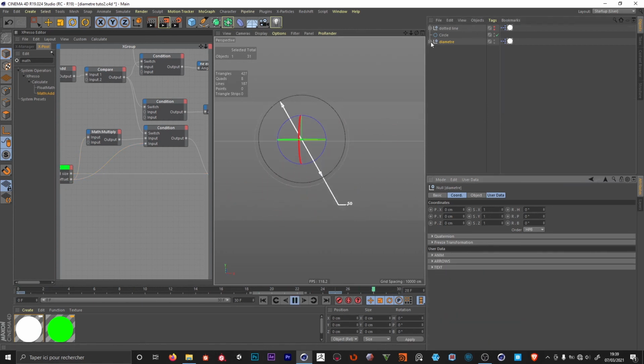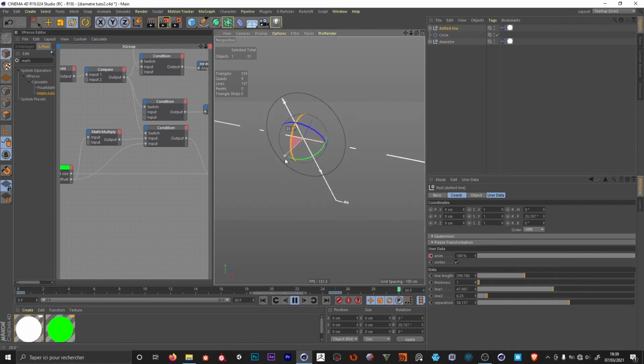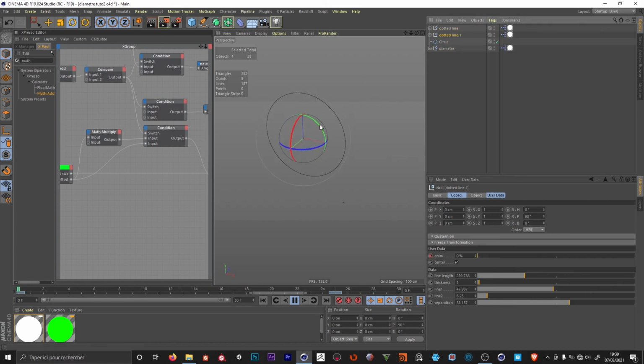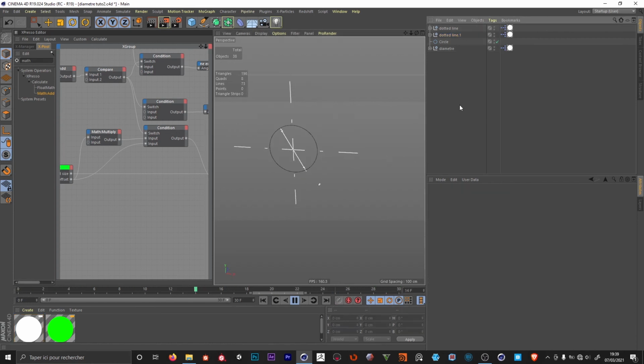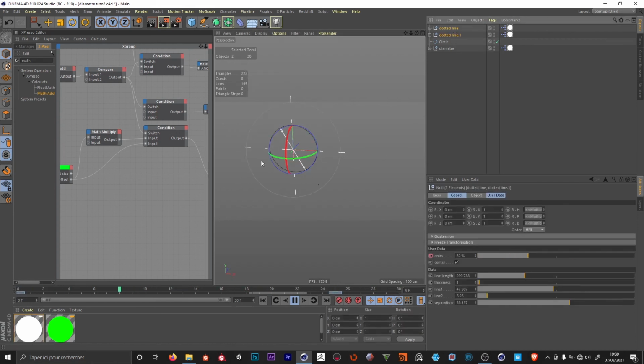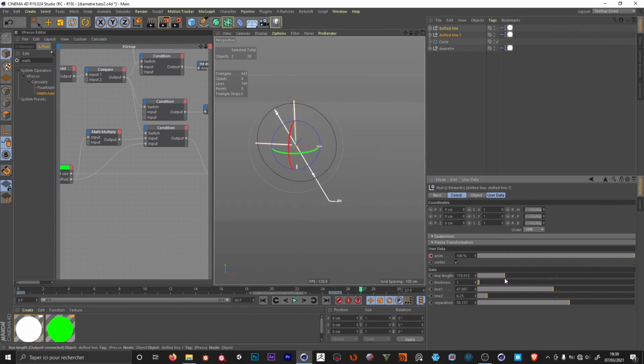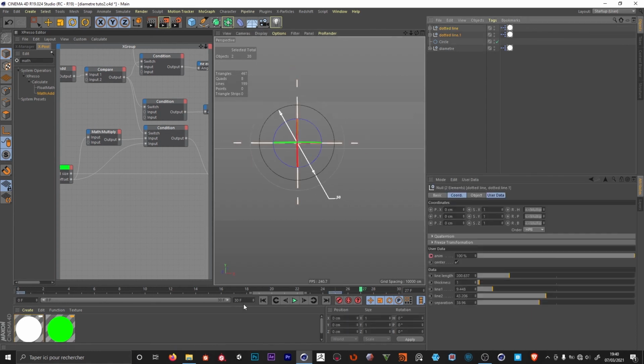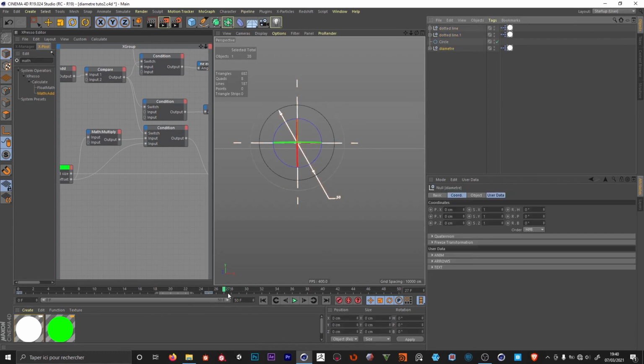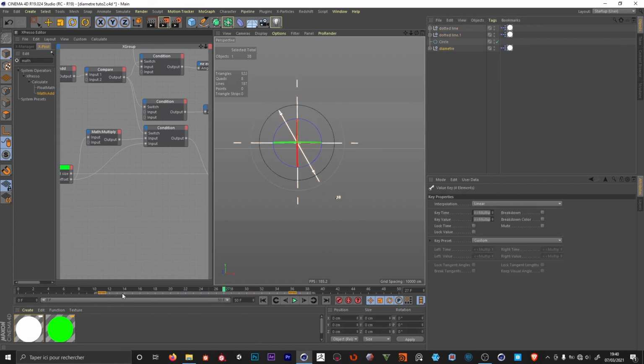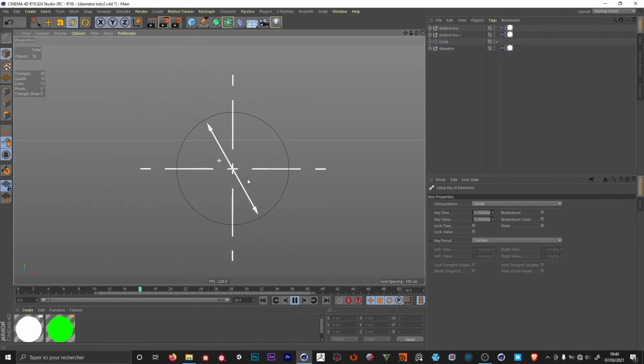We could now bring back the lines we did in the last video. I'm going to just rotate it 90 degrees. I'm going to control drag, set it to vertical. So we have our little animated diameter. We could select both lines, make them shorter, play around with the parameters. I'm going to increase the timeline to 50 frames. We could now offset the animation of the arrow. So we got the little animation here.